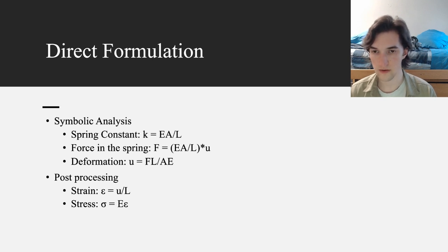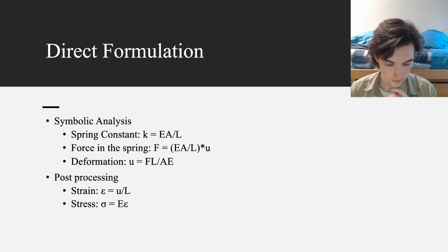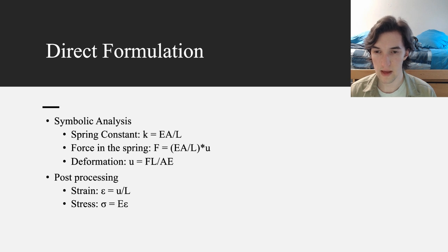Additionally, the water from the pipe would hit any teeth that we may add to the deflector later on, which would create a force that's perpendicular to the axial force in this model. Moving forward, it would be good to use FEA methods in 2D and 3D, as well as any FEA methods for fluid dynamics for the water. For now, the direct formulation is good enough to model this.